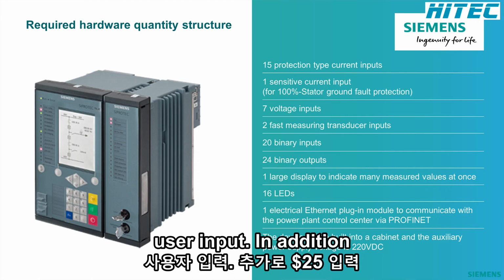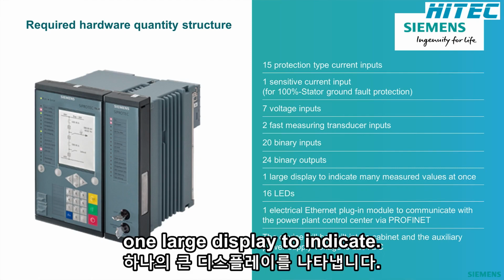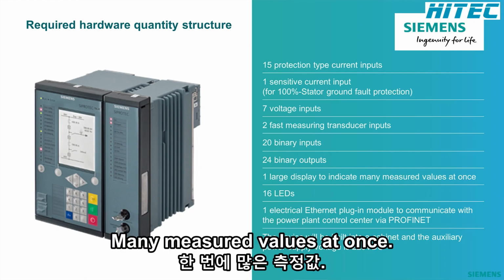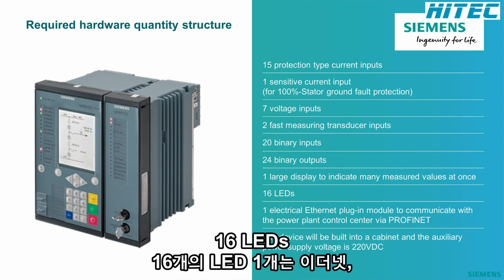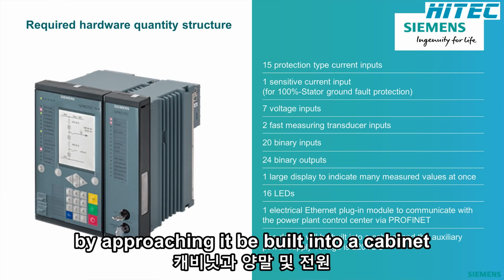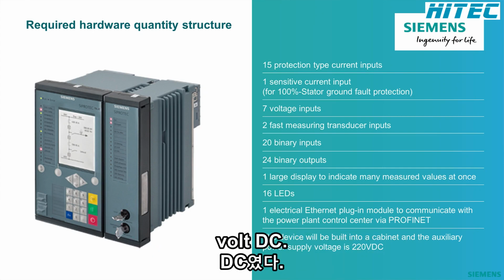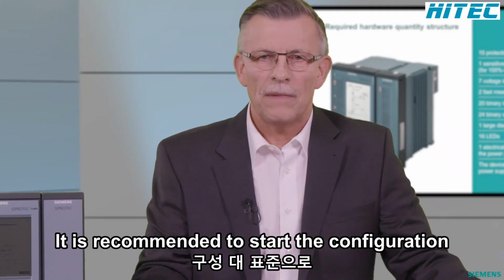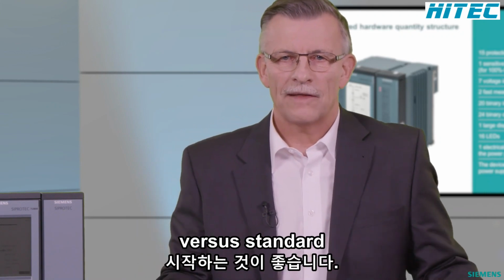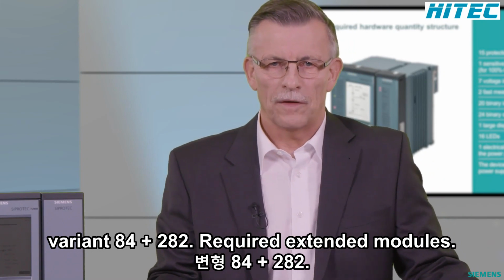In addition, 20 binary inputs, 24 binary outputs, 1 large display to indicate many measured values at once, 16 LEDs, 1 electrical Ethernet plug-in module to communicate with the power plant control center via Profinet. The device will be built into a cabinet and the auxiliary power supply voltage is 220 volt DC. It is recommended to start the configuration with the standard variant AA4 and to add the required expansion modules.